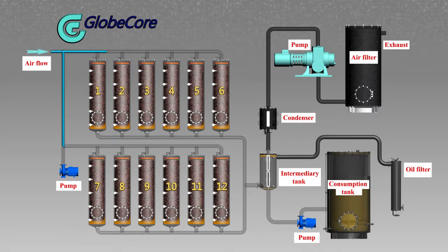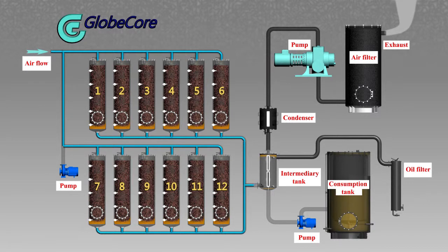When the reactivation process starts, the heating system switches off. The vacuum pump creates the airflow for sorbent reactivation. All oil decomposition products are burned and are expelled from the machine after catalytic breakdown into safe, non-hazardous compounds. Reactivation lasts until the sorbent cools down entirely, which is indicated by cold air in the exhaust system. After reactivation, the control system refills the system from the consumption tank and switches the unit into oil regeneration mode.